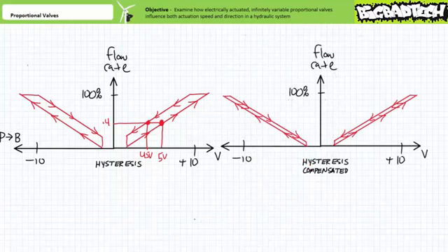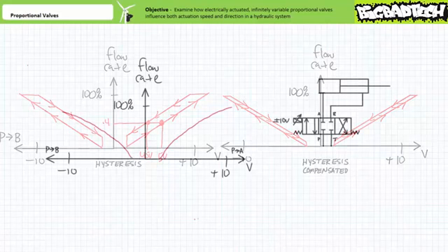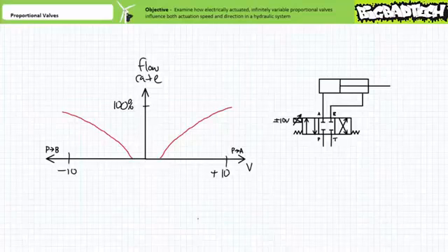The flow rate through a proportional valve properly compensating for hysteresis as a function of applied voltage would look like this. The deadband would still exist, however, flow rate as voltage ramps up is a little bit more equal to flow rate as applied voltage ramps down. By the way, a real flow rate as a function of applied voltage curve might not look as neat and linear as these previous simplifications may have suggested. A real one might observe a little wiggle waggle. However, if you squint your eyes just right, you can see the linear approximation.